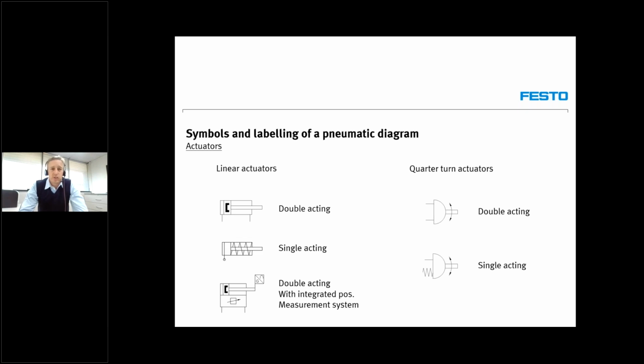One way to find out is to connect a differential pressure gauge across that filter unit, and let's say after 2 or 3 cycles, you will find out that after 2 months or 3 months or 6 months or a year, your differential pressure will increase, and you will then need to replace those filters. So there's no specific indication of when to replace the filter elements or service the filter units. It depends completely on the operation, how much air is going through that filter, and what the air quality is. Unfortunately, it's going to be by trial and error.